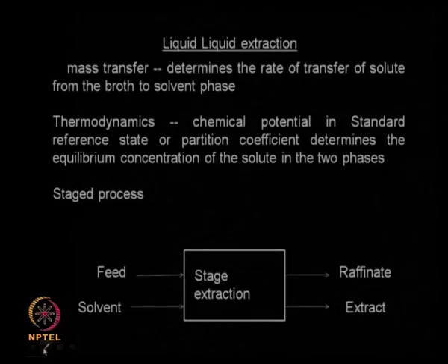There are two important principles in liquid extraction. One is the thermodynamics, other is the mass transfer. Mass transfer determines the rate at which the solute moves from the heavies or the fermentation broth into the solvent layer. So if the mass transfer rate is very high, the movement of the solute is very fast, so we can achieve the extraction very fast. If the mass transfer rate is very slow, then the extraction efficiency is very slow.